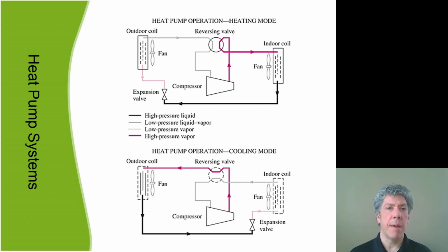One interesting thing that can happen when an air conditioning system is losing its refrigerant, if there's a leak somewhere, is the indoor coil temperature will actually go down farther. It'll go down to the point where it does in fact ice up. And so if you have a repairman come and he says, well, you got ice on your coil and you need more refrigerant, you might think, wait a second, seems like the refrigerant's working great. I mean, after all, there's ice on the coil. Wouldn't that mean there's too much? Actually, that's not the case. It means there's too little. You want to add refrigerant so the temperature doesn't drop quite so far and block flow across the indoor coil, because then your air conditioning system doesn't work right.